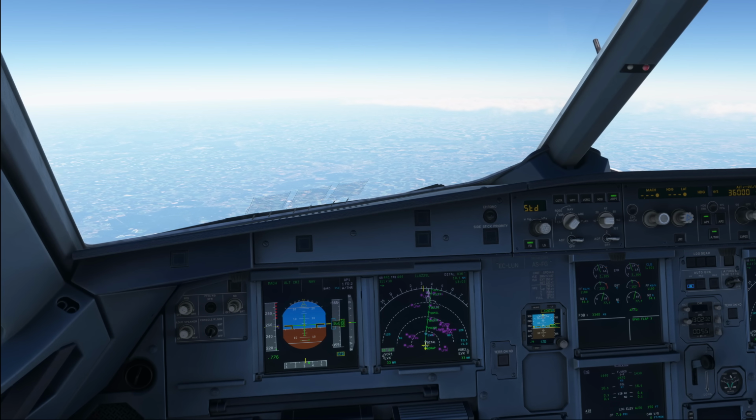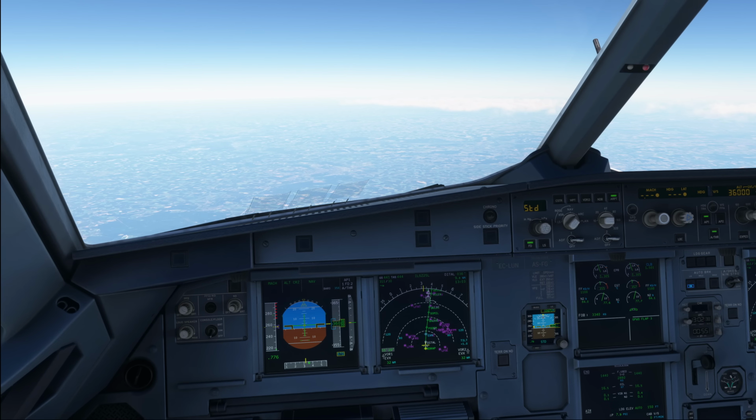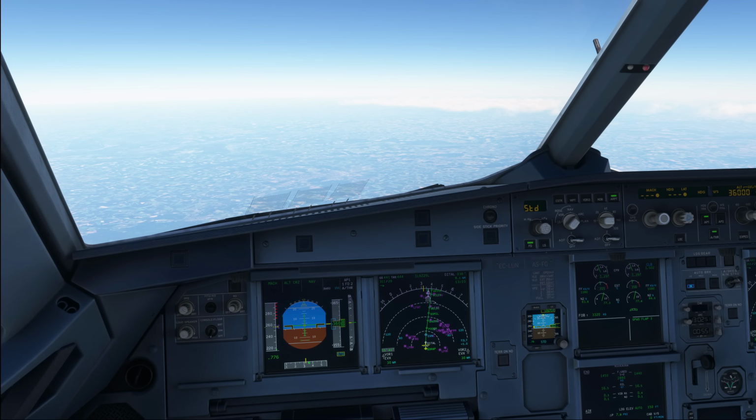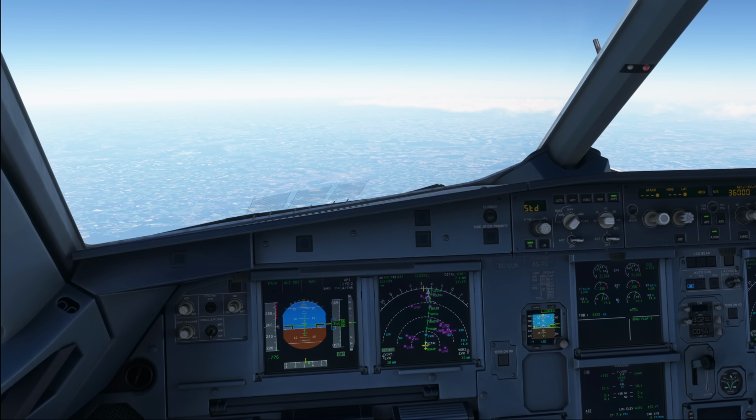So then going on to the next point here, which is before pushback or start. When conditions and air traffic control permit, the flight crew should delay the engine start for as long as possible. This is to reduce time spent with the engines running before takeoff. And before takeoff, the flight crew must ensure engine warm-up in order to prevent engine wear and to maintain engine performance. Single engine taxi obviously is something that can be taken into account and that we will talk about in a few moments.